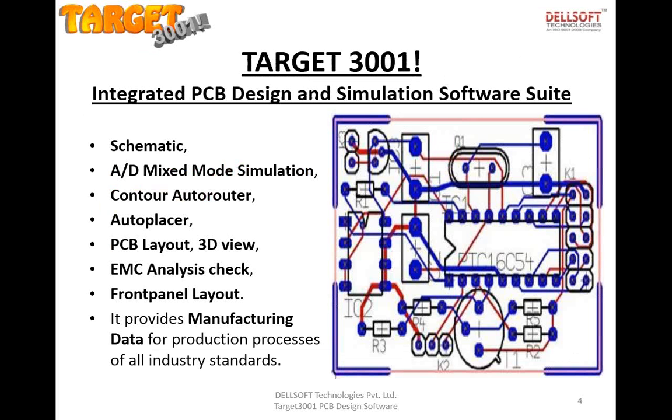Now, it is an integrated PCB design and simulation software, and it has various features like schematic for doing the entries for designing any circuit. You can drag and drop simply the components into the environment and create your own circuit. Then there is an AD analog digital mixed mode simulation for doing any simulation for transient analysis, AC analysis, DC analysis, and there are probes available to analyze the voltage and current at a particular point.